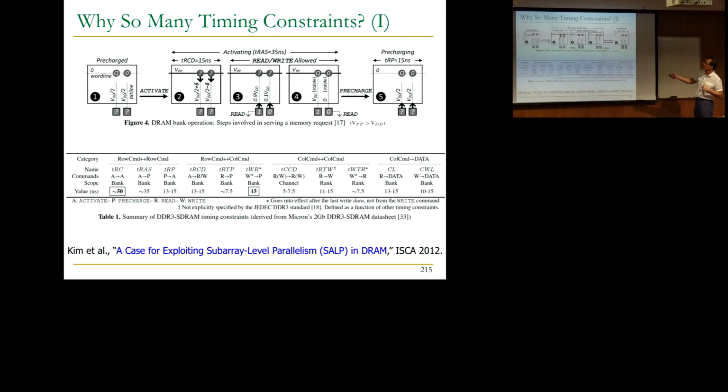Basically, as you can see, this was VDD, this was 0. We're looking at only 2 cells. It's actually 2,000 cells over here or so, whatever the row width is. You basically need to set all of the bit lines, 2,000 bit lines, to VDD over 2, and that takes some time. There's a pre-charge circuitry that does that, and that's about 15 nanoseconds over here.